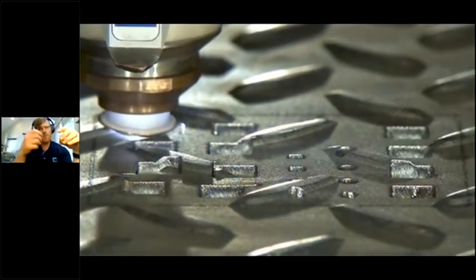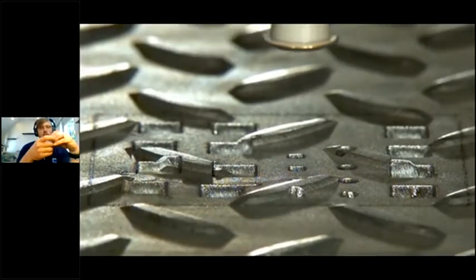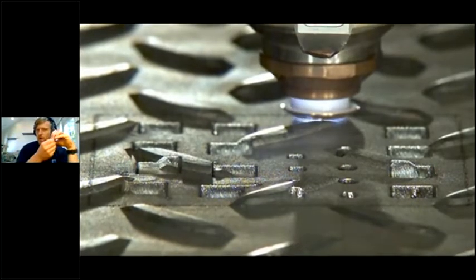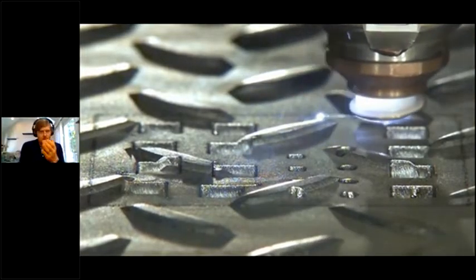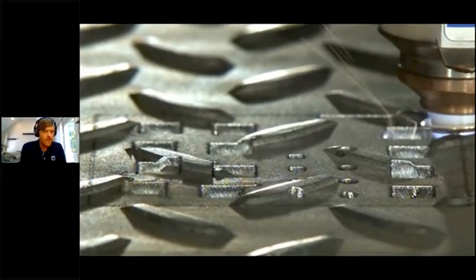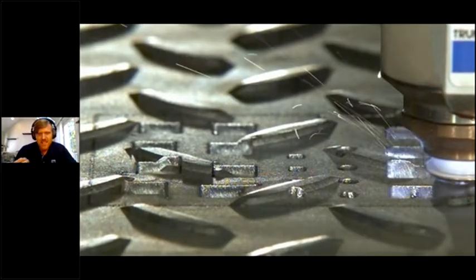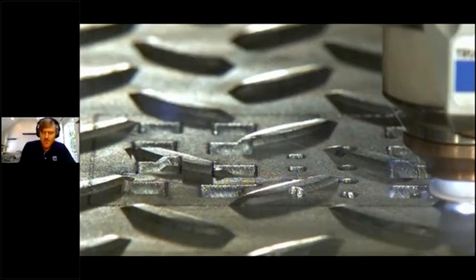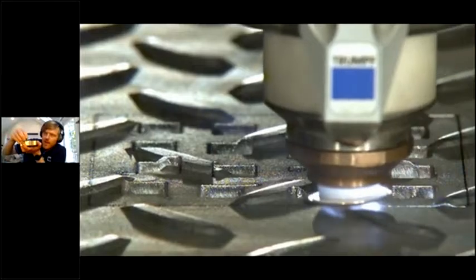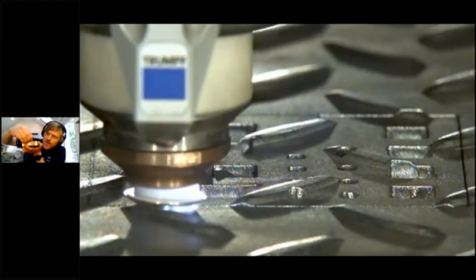Now, this will probably consume the sleeve a little more quickly. So if we're cutting with this sort of process on diamond plate or something that has a rough texture like this, you might go through the sleeve a little more quickly. But that's really the upshot to a nozzle like the Highspeed Eco, or indeed the Highspeed nozzle: in neither case do you have to worry about the nozzle being so close to the material that it becomes problematic, where it's potentially hitting a little bit of slag bulging, a little chunk of 1-inch stainless steel. With other nozzles, you might have to be very gentle on that pierce, because if it's sitting right off the surface, it's going to hit that.